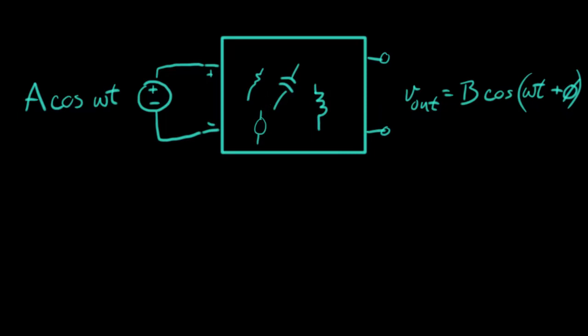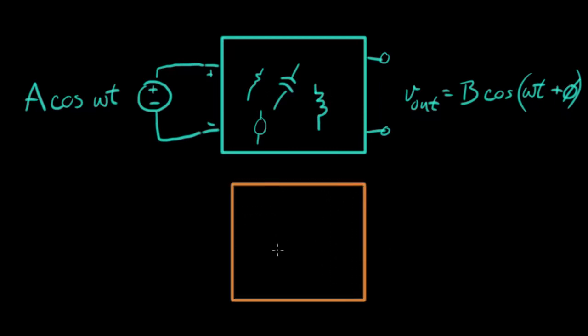Now, what we do with Euler's formula is we turn it into exponentials, and we already know how to solve exponentials. So we take the same circuit. It has the same stuff inside it, resistors and capacitors, the same exact circuit. Let's draw the same exact circuit there. That's identical. And it has the same output port right here. And this time what we're going to do is take this cosine and cast this into an exponential. And the way we do that is we use that formula.